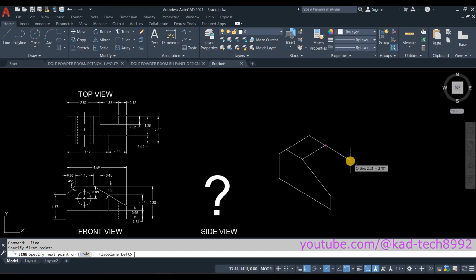Press F5, 0.48, and then press enter, and then we copy this line, move it here. Let's make a line here so we will know where to trim our line.